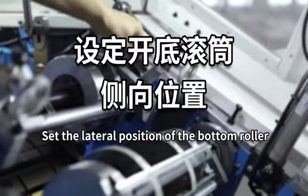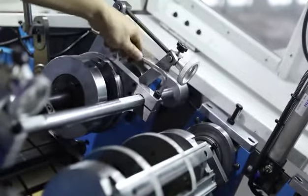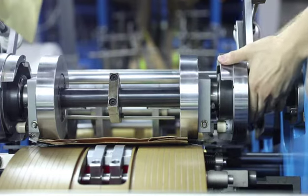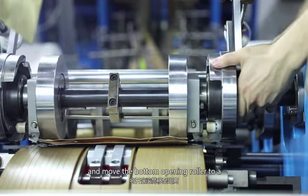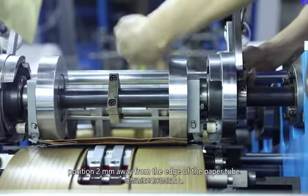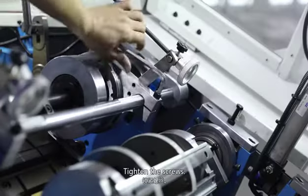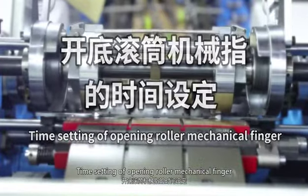Set the lateral position of the button roller. Loosen the screw of the cam fixing seat of the button roller. Move the button opening roller sideways to a position 2 mm away from the edge of the paper tube. Tighten the screws.